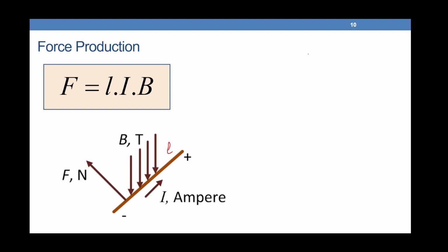So if we have the conductor we had before and we apply a flux density B in this direction, and we succeeded to pull this one by a velocity V meter per second, there will be induced voltage E in this direction, and we connect a small resistance R here, so we succeed to push a current I in this resistance.